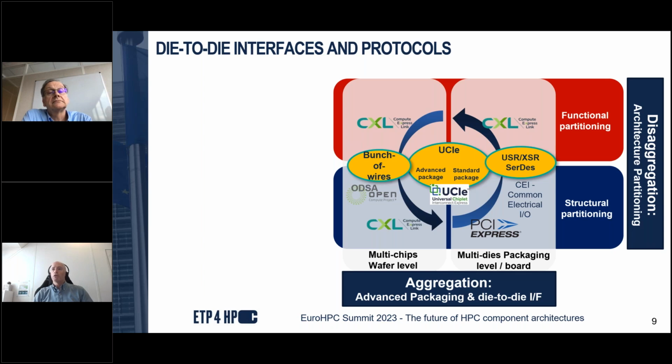As a chip maker, this offers a lot of advantage because you would see one interface. One of the challenges we have as chip makers is what we call beachfront, the edge area of the silicon, and optimizing that. Having one interface that could optionally connect to different kinds of the high speed interfaces, integrated into a single kind of interface, would give us a lot of flexibility in how we design chips. So that's the promise of CXL today. And then if we integrate that with silicon photonics, as we talked about before, this would allow disaggregation at the system level efficiently.